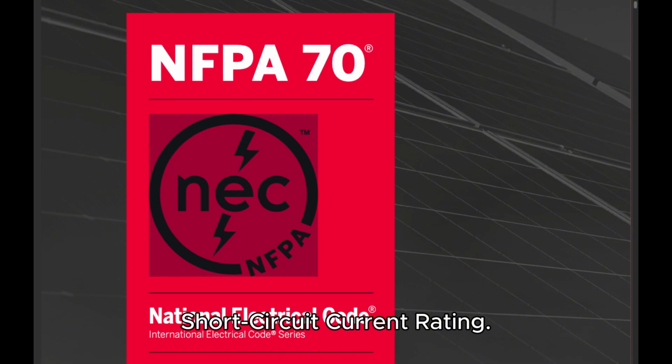Short circuit current rating. The prospective symmetrical fault current at a nominal voltage to which an apparatus or system is able to be connected without sustaining damage exceeding defined acceptance criteria. CMP10 show window. Any window, including windows above doors, used or designed to be used for the display of goods or advertising material, whether it is fully or partly enclosed or entirely open at the rear, and whether or not it has a platform raised higher than the street floor level.